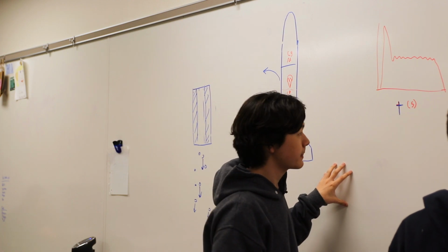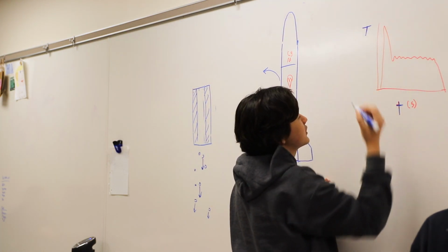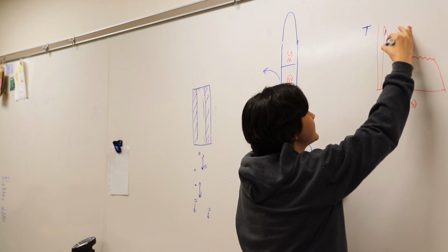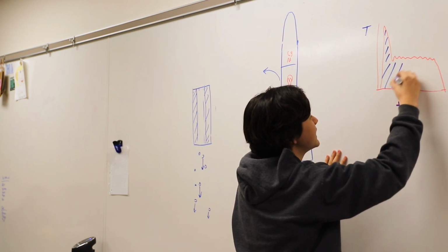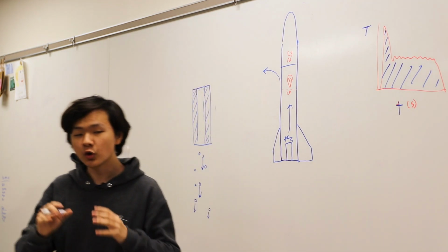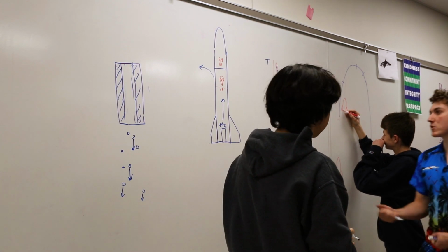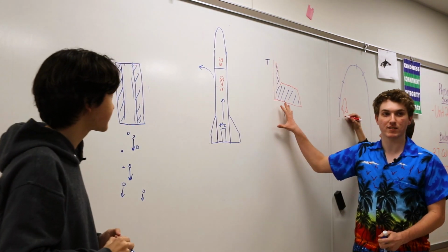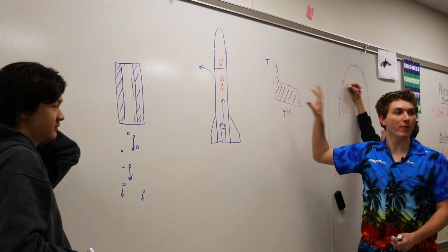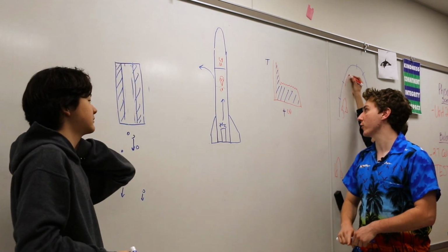If you look at the thrust versus time curve, and you take the area underneath this curve, which is called an integral, you get what's called an impulse, which is basically the total amount of thrust that you're going to be putting out over time. Most of the time when we're doing this, we're not doing the hard math of calculating how much force is applied at each time. We generally just make computers do that because it's a lot quicker, easier, and more accurate most of the time.